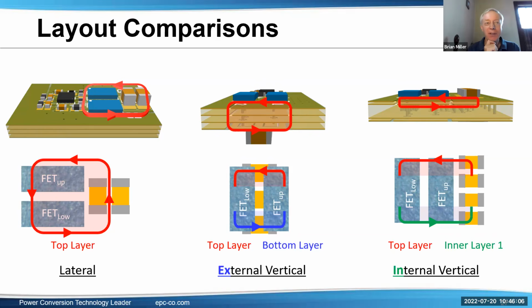Maybe the first pulse, but with the bootstrap capacitor and so forth, once the capacitor is charged up for the upper gate drive, the speed of that charging up and so forth doesn't really matter that much unless it's a very extreme duty cycle. But I don't think we've really seen that show up as an issue. Okay.